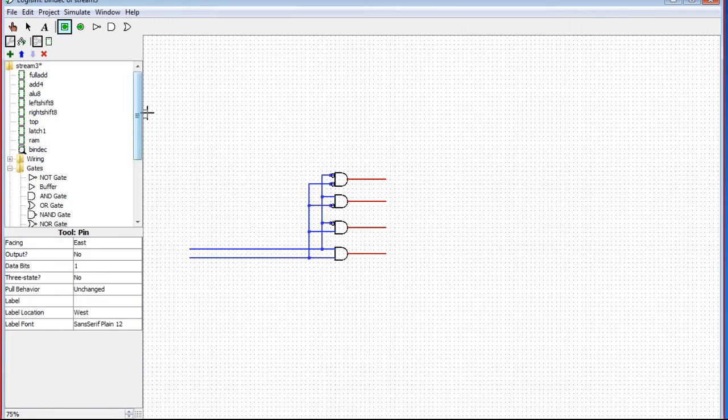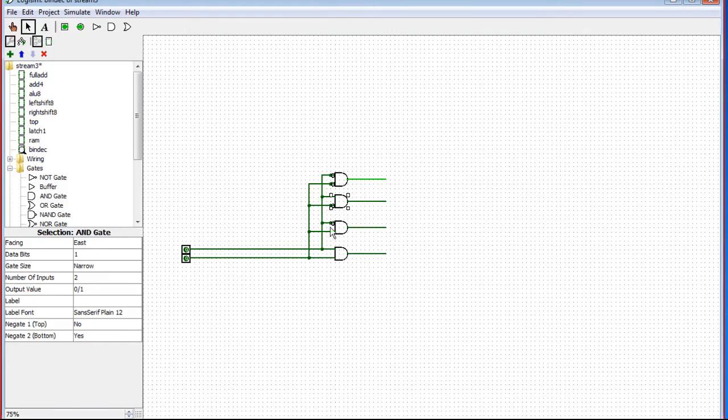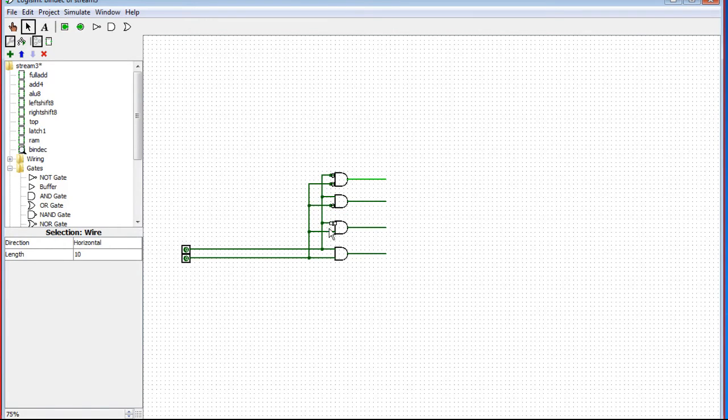Let's test this out. And you just put NOT gates on those, or yeah, what typically? Yeah, it's basically putting NOT gates, but when you actually look at the transistors, it just uses different transistors. It doesn't add any transistors to add these inverters on the inputs. I think it just swaps P-type for N-type, or maybe it changes the layout. I'm not sure.